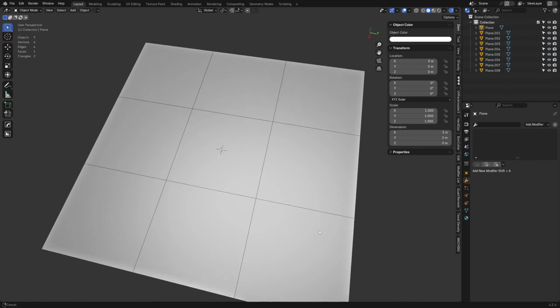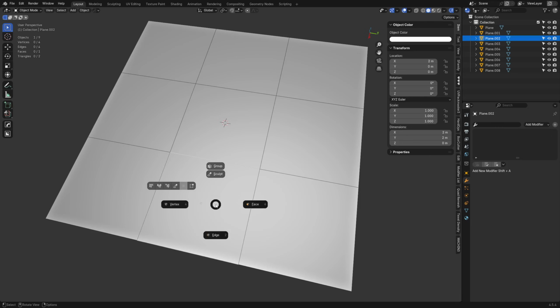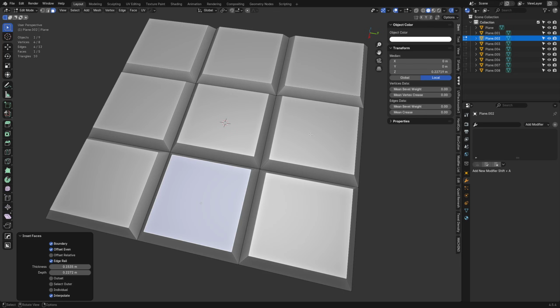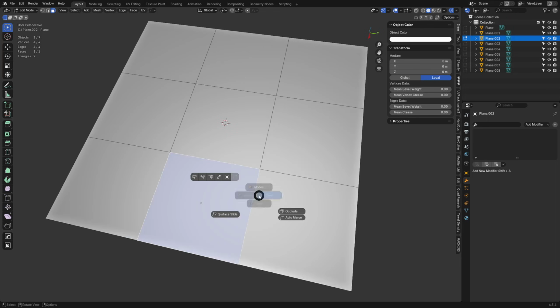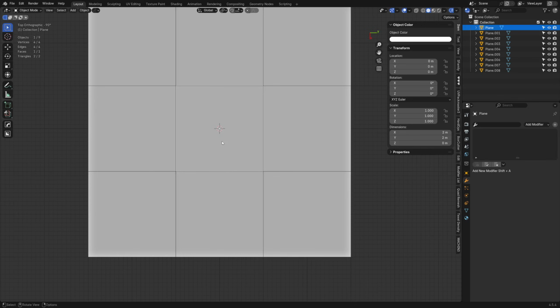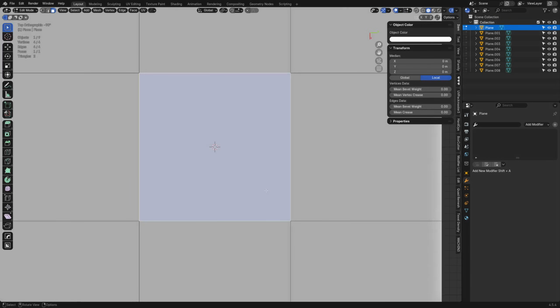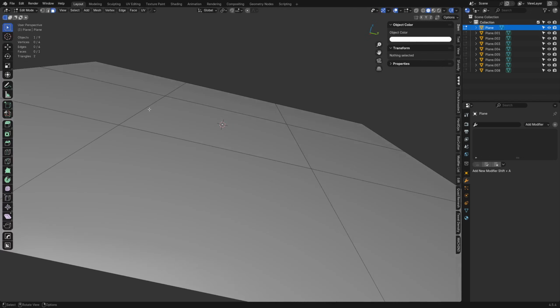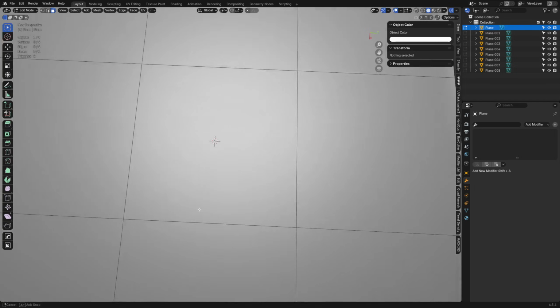What this is, they're the same mesh repeated. So if I took one and inset it, hold Control, you see they all do the same thing. So this is good because if we're going to cut out something like a seamless tile, you can do that very easily here. But you do got to be a little bit particular on how you approach this. You don't want to move anything on these edges. You can only move them up and down or left and right. You don't want to move them, in this case, forward or backwards or whatever.